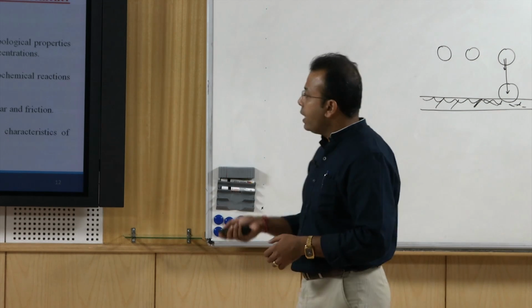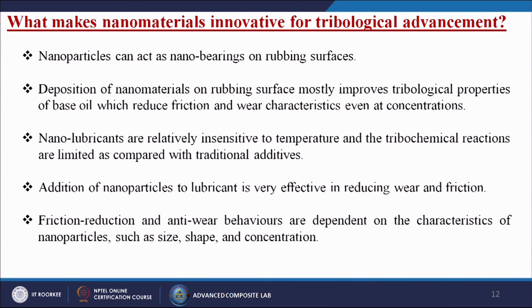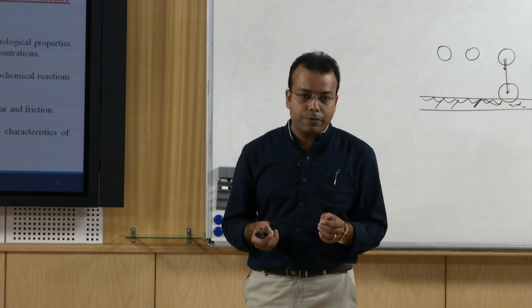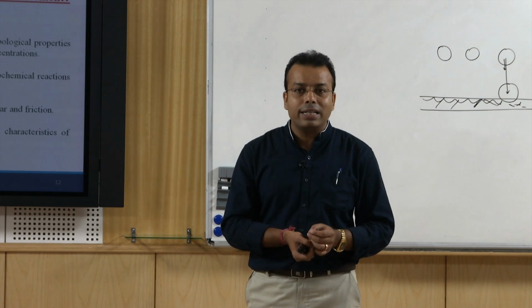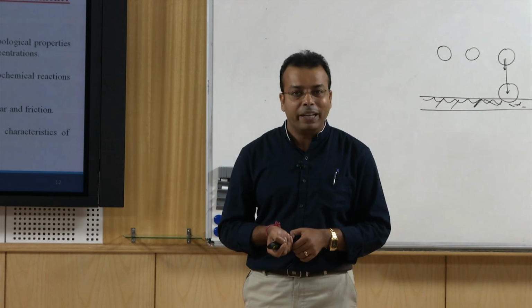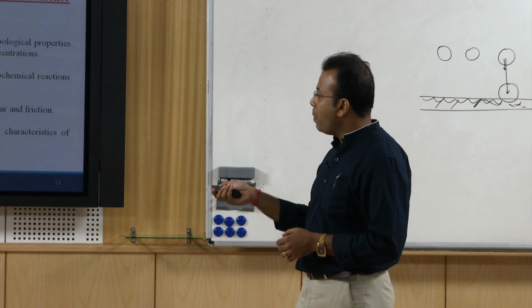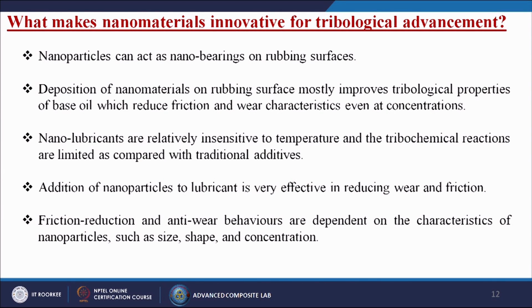Next, nano lubricants are relatively insensitive to temperature and the tribochemical reactions are limited as compared with traditional additives. These are less expensive and can be easily fabricated in the lab itself, so they have wide applications. Addition of nanoparticles to lubricant is very effective in reducing wear and friction.